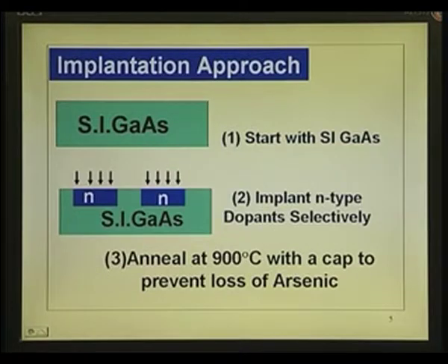Here you can implant silicon or sulfur, whatever you want, with a single machine by controlling the trajectory path of the implanting ions, because the mass is different, that governs the voltage and the path. So, you can choose particular implanting species. At a time, of course, you implant only one. So, there is no question of choosing between them, but once you choose the material, you have to make certain adjustments so that the particular curvature path is followed.